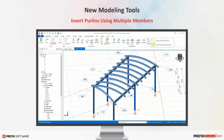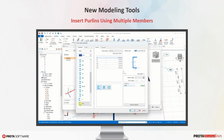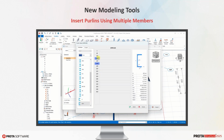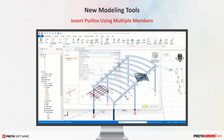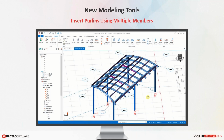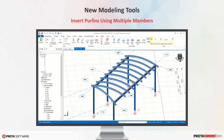You can now directly select the primary members which will support the purlins. This allows you to insert purlins more precisely. We still keep the previous first and last member insertion method as it is, because it is very fast actually. But this multiple member selection method provides more flexibility, particularly if your primary members are not following a linear path, like the case shown here.